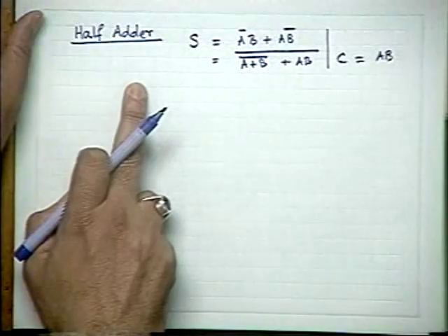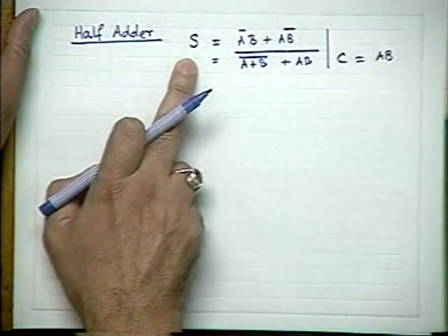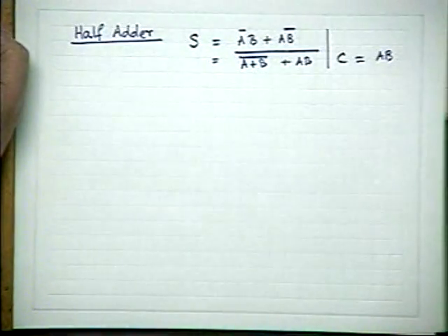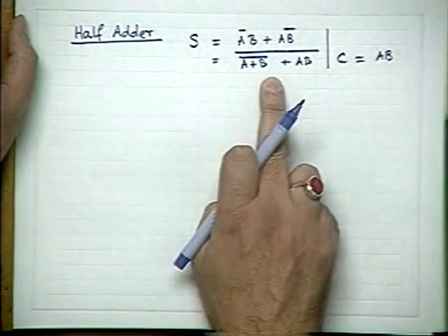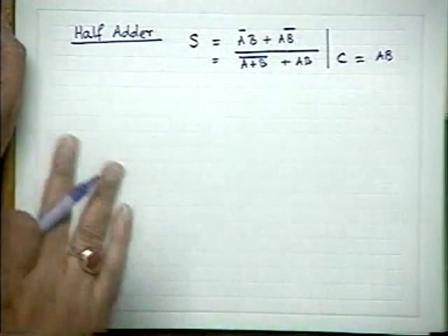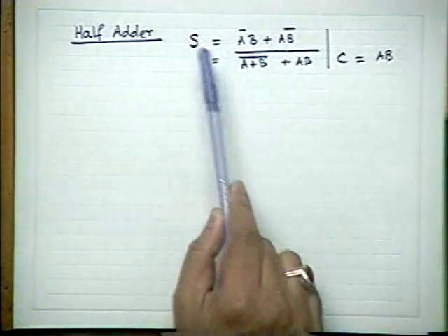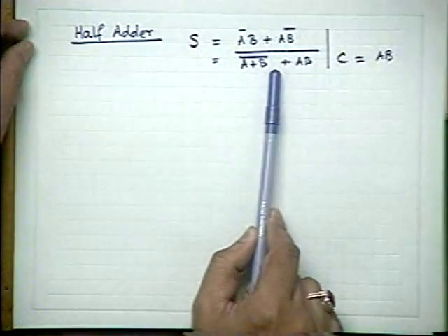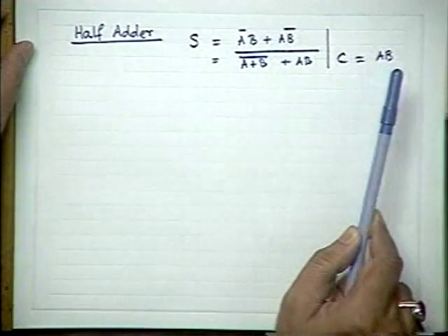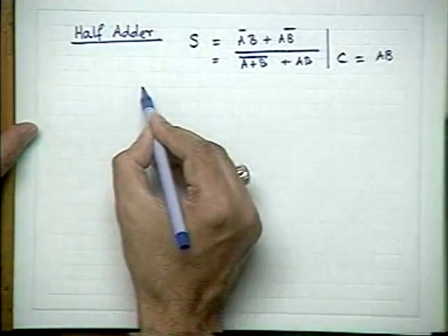So in the case of a half adder, where sum is nothing but the exclusive OR of A and B, you can write it like this for my convenience here. We shall see, because it is the easiest. If we could use a NOR gate, it is the most convenient in I square L, and therefore I have written it like this. I have just re-expressed it like this. Whereas AB is very simple. You can use the complements of inputs and just pass them through a NOR gate to produce it. So let us now see. Basically, therefore, your circuit is like this.